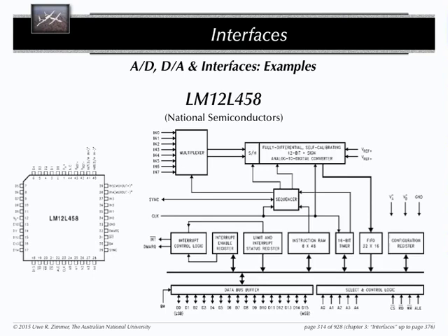You need to tell it, for example, when, how precise, how fast, how frequent. And you need to get the data out of the AD converter, finally accessible to a computer system. This is, as I said, in most modern computer architectures, done via a memory interface, via the bus system. And what you see down here is a bus interface.